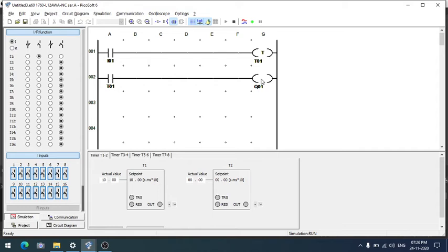For example, a sensor senses something, and I want to switch on some fan or some device only for 10 seconds, then it needs to go off. In that case, we can use this, right? It will pick up the sensing output, then it will enable the timer for 10 seconds. So the output connected to the timer will be enabled only for 10 seconds, then goes off.